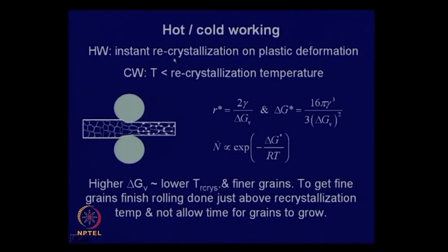It also depends on the rate at which the deformation is given, and on the amount of deformation. So it is not a fixed quantity, and if we understand the factors that determine the recrystallization temperature, we will be able to design a thermomechanical processing route by which you can get the best combination of strength and toughness.